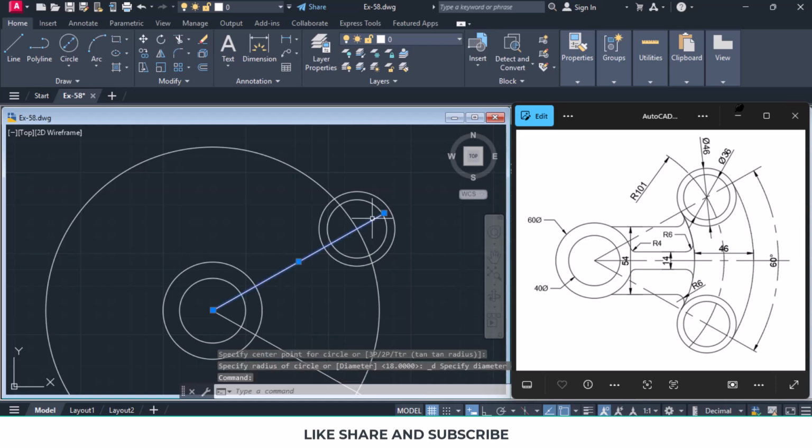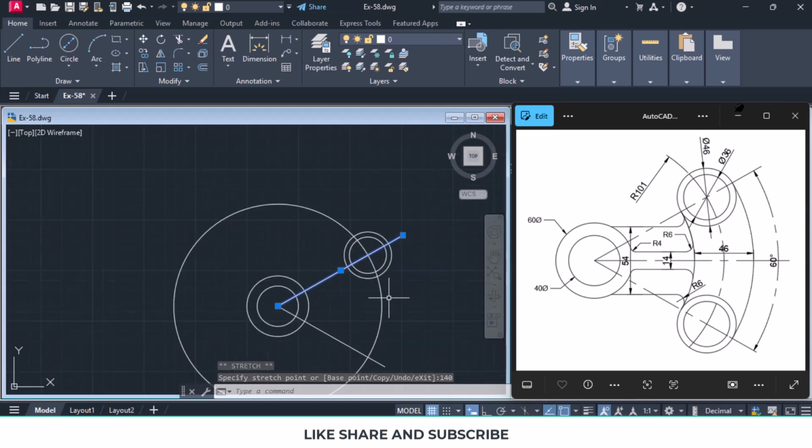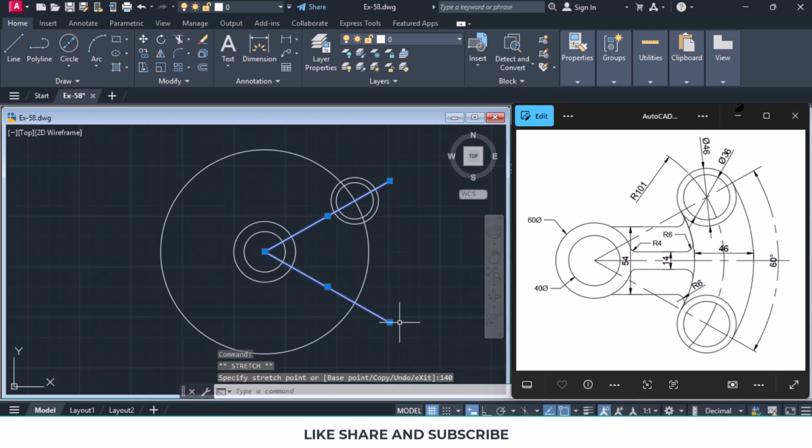Now this line is there, we'll stretch it further so that it extends beyond the circle. So we'll press shift and tab so that we come to the length of the line, and we give the line length as 140 and hit enter. So it extends a bit beyond the circle. And same way over here for this line also, we click over here and we give the distance for this line. We press shift and tab, 140, and hit enter.